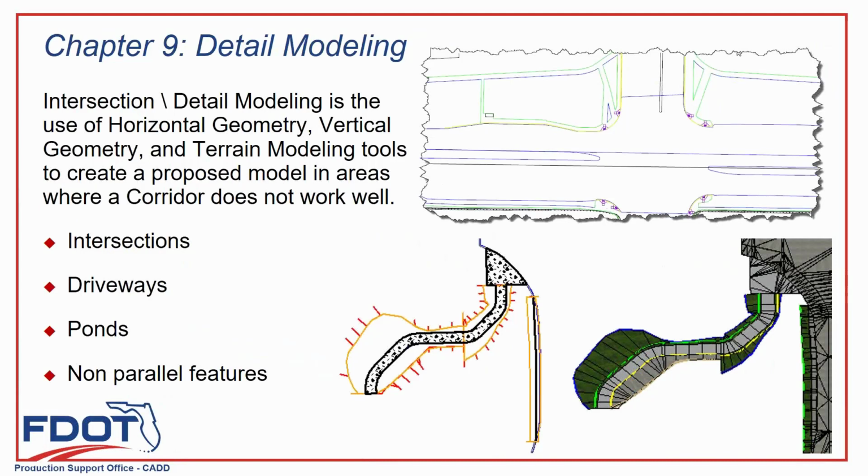So it's an iterative process, right? You find where the two meet, and then you target both to that line. So you first build it to the existing, and then you come back and say, all right, that's the line, target it right there. And it builds a nice seam between two corridors, because that's going to be important when you go to do earthwork files.